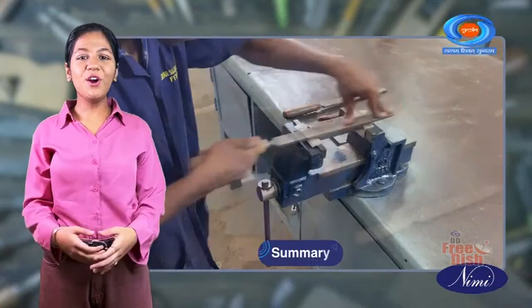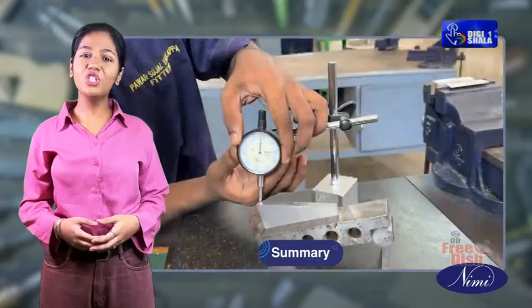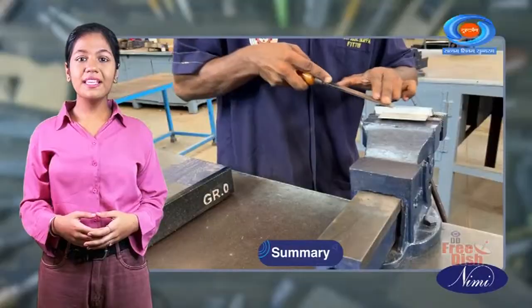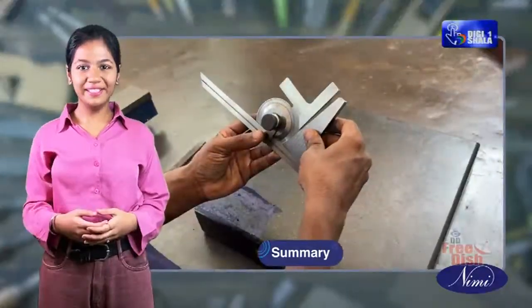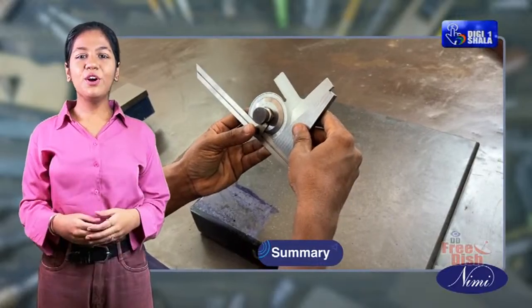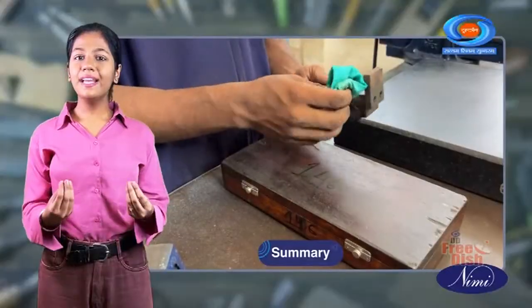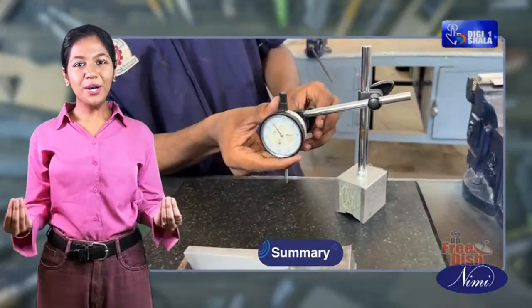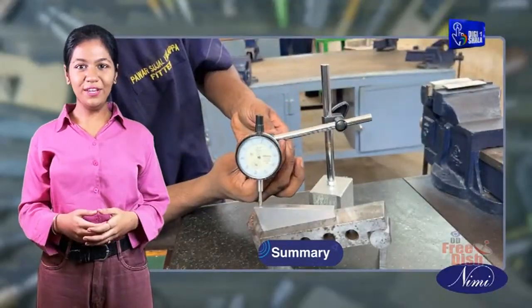The topic revolves around scraping an external angular mating surface and checking the angle using a sine bar. Scraping the surface involves the removal of material to achieve a precise angle. This process involves several steps including cleaning the surface, setting up the sine bar on a flat reference plane, mounting the workpiece and positioning a dial indicator to measure the deviations.